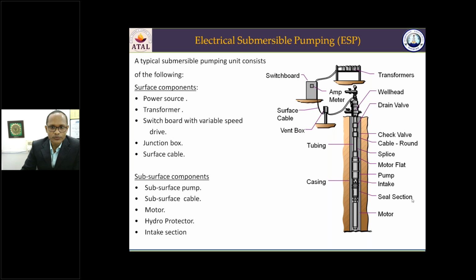Above the motor, we have the protector, or the seal section. This seal section connects the motor to the pump. There are thrust bearings here, high capacity thrust bearings. So it connects the motor to the pump, and also it acts as a reservoir of oil.